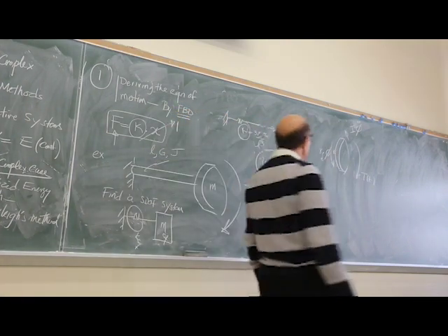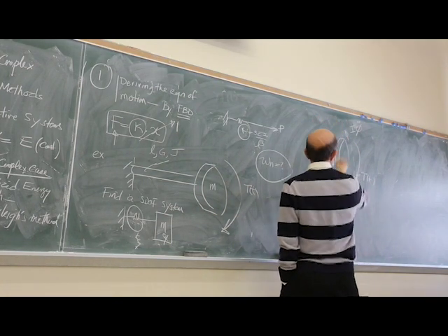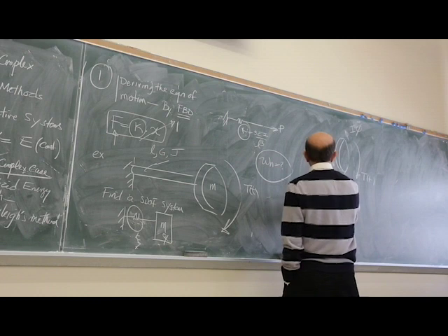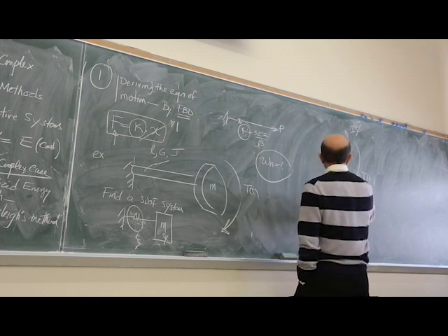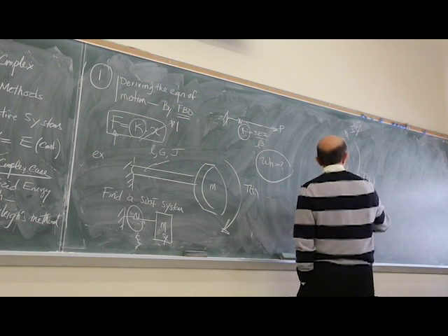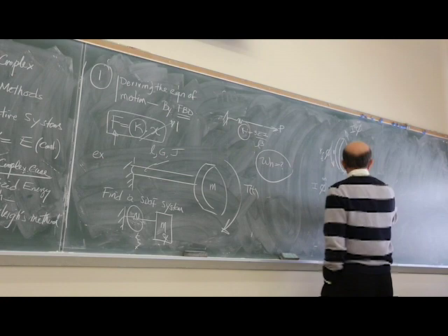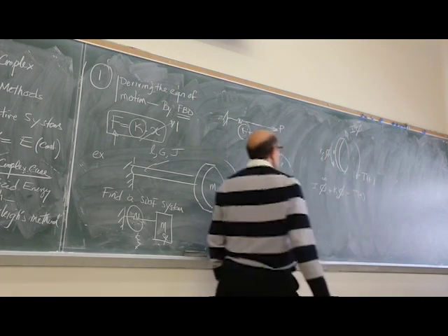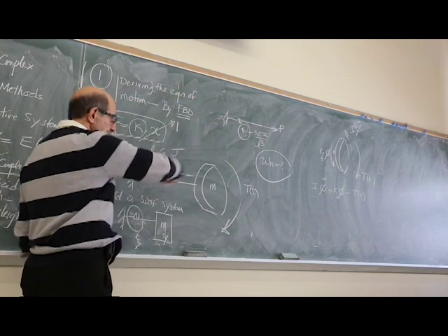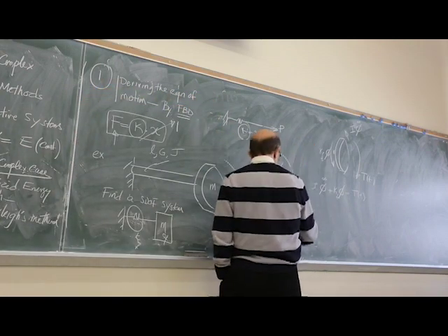right? So the equation of motion then, simply just from this free body diagram, would be I phi double dot plus k times phi is equal to T of t. But what is k here, k sub t? Remember the beam that I drew? Shaft is very similar.